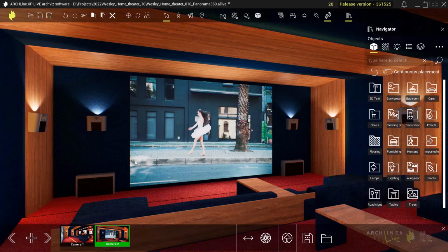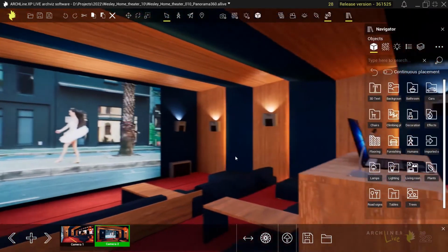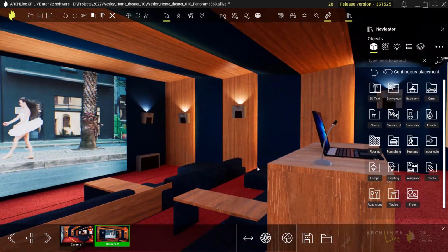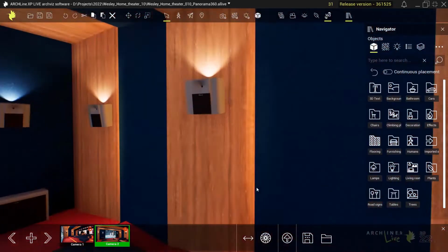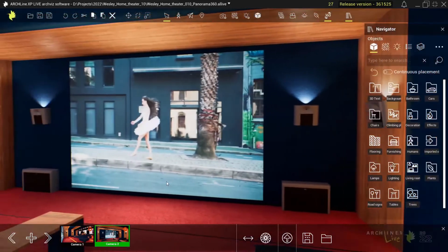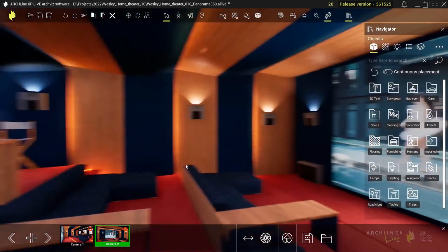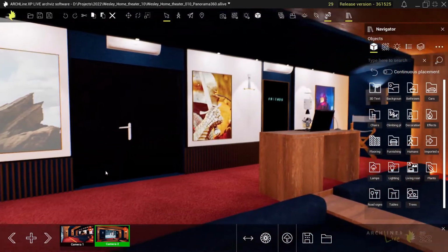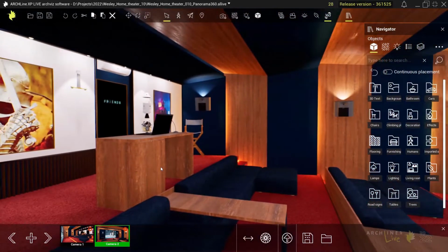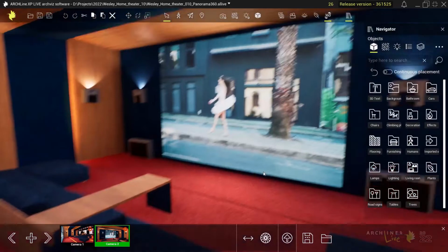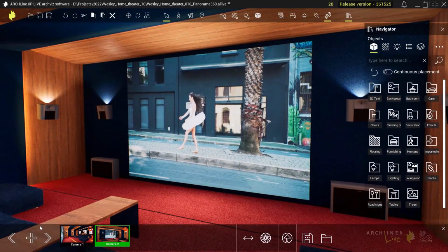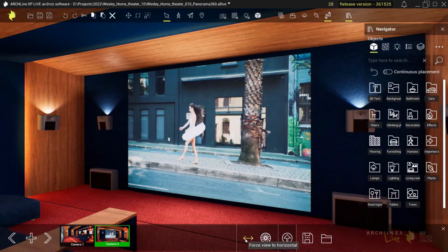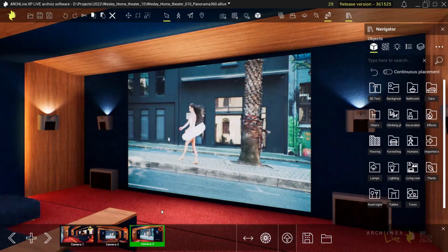Let's find a nice spot for camera 3, and that should be somewhere around here at the staircase. So let's dolly in, pan a little bit if it's necessary, and turn around. I think this will be a nice place to look around from, so they can have a good angle looking at the entrance and all sorts of other details of this interior. I think this will work very well. So let's just keep it as it is and add it to the view. Again, if I would like to, I can force the view to horizontal, and then add it as the third camera into this list.